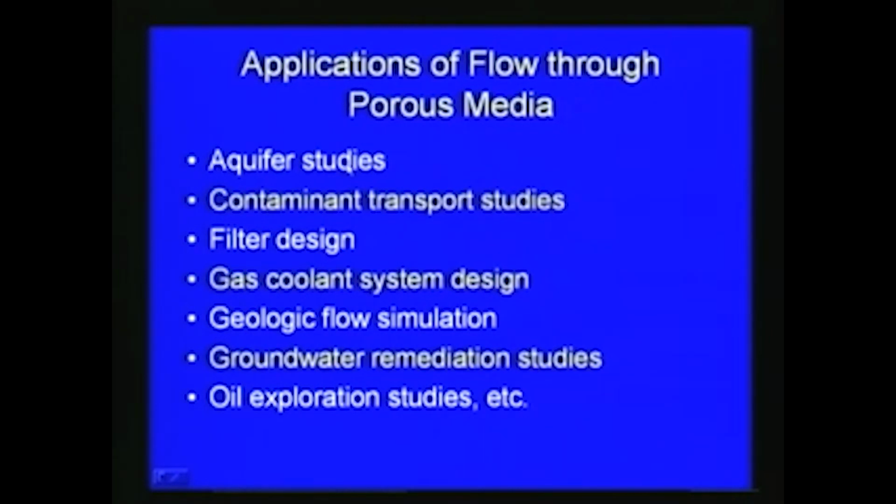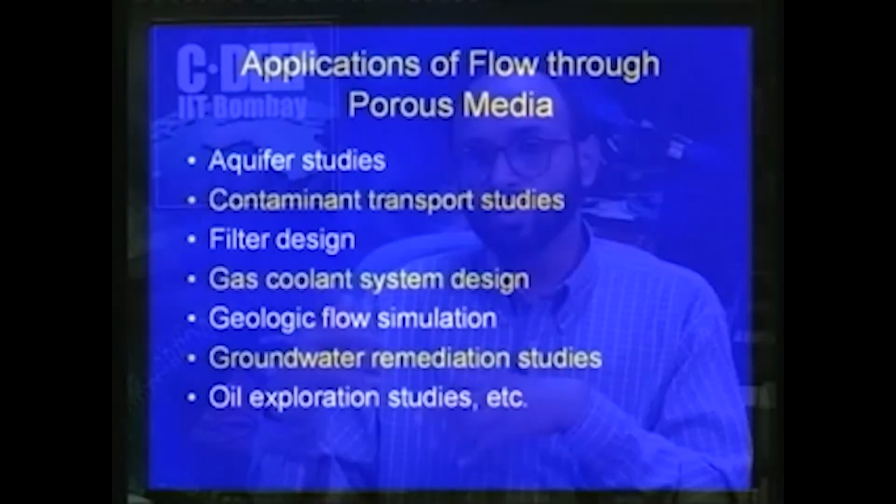This flow through porous media has a number of applications, like we have already seen in aquifer studies, then contaminant transport studies, filter design, gas coolant system design, geological flow simulations, groundwater remediation studies, oil exploration studies, etc. This is related to groundwater flow, for which a course can discuss it in detail, but the aim of this discussion is that we can start from the Navier-Stokes equation, get the simplified equation for porous media flow, and for simple cases like steady state flow through homogeneous isotropic media, get a solution.